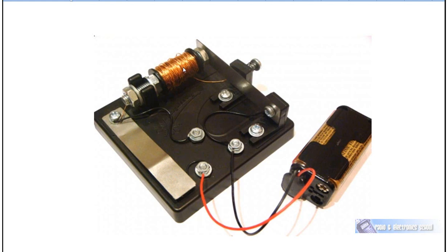So if your finger's down on that, making a circuit, we've got a complete circuit. Every time the electromagnet becomes magnetized, it pulls this armature in towards the head of the bolt. When it does that, it opens the circuit. The screw here is not movable, so when this armature moves inwards, it actually breaks the circuit and turns the current off.